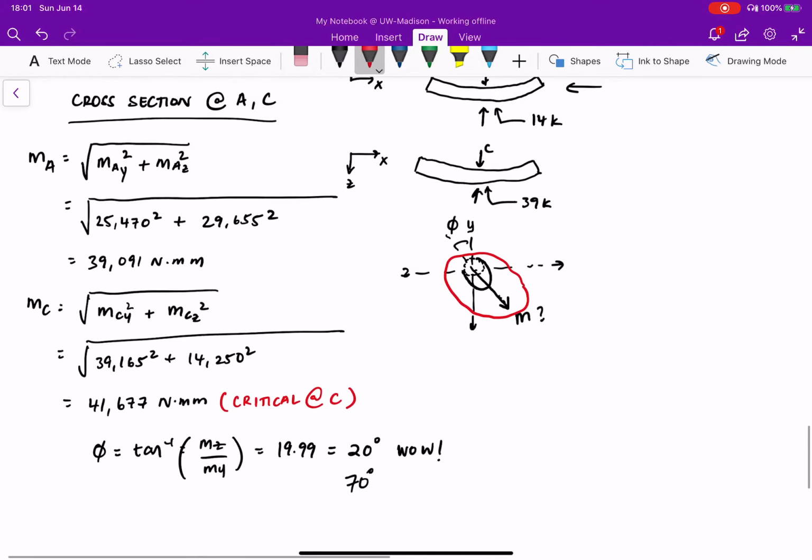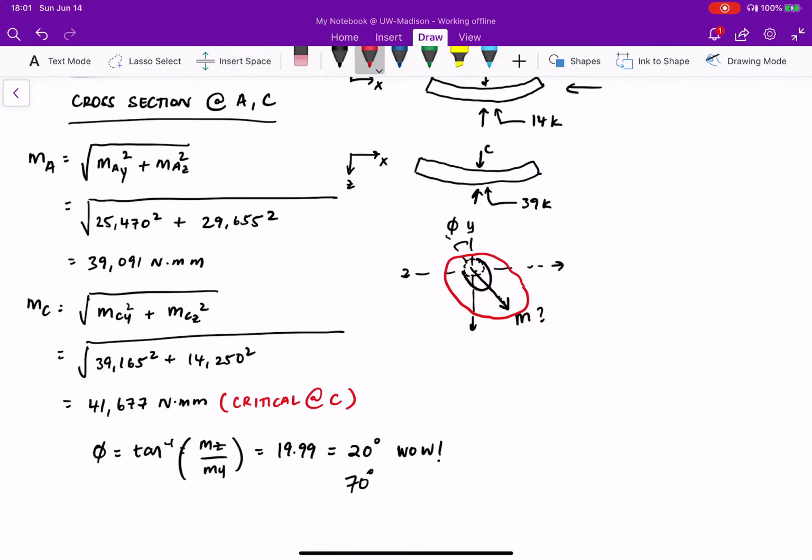And as we get into gears, you will see that that angle is called the pressure angle. When you have two mating gears, the force acts along a line that's 20 degrees off from the XY coordinate.